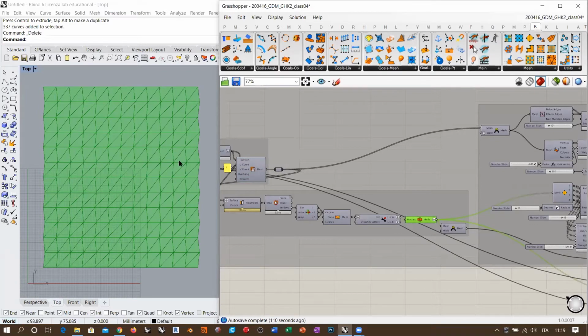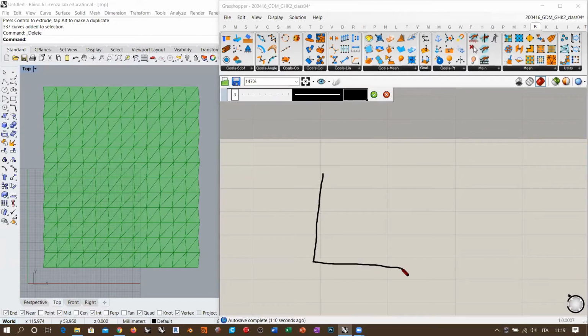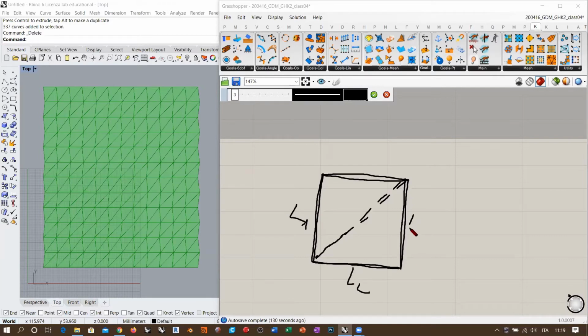This means that if I have this quad here with a diagonal edge that I am not taking into account for the elastic properties, then this edge, this edge, and this edge, with length 1, length 2, length 3, and length 4, will be constant during the simulation. But this one, no, it won't be.